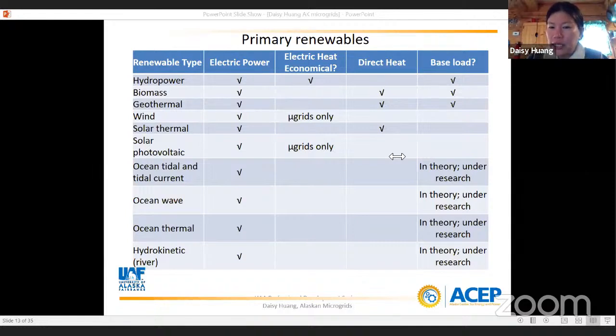But what they did was they installed in several of their houses, starting with the elders' homes so they could benefit first. They're native communities, so they're elder-honoring peoples. They put resistance stoves in these people's houses. It's basically a big resistor, like the big toaster I was telling you about, embedded in a ceramic brick. When there's excess wind that the grid cannot use for electricity, they heat up those bricks. So it gives space heating. It feeds the heat demand in the house based on a fan blowing over the brick. When it's getting cold in the house, a fan will blow over the brick and heat up the house. When it's getting warmer, turn off the fan, and the brick just sits there.